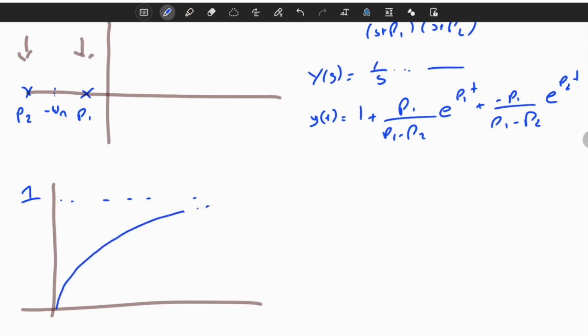Okay, so as you can see, it is very similar to the critically damped case. That's nice. Now the question is, how fast will it go, or which part will dominate the behavior? The basic idea is the fast part. Because this is constant, I have 1 and 2. The fast one will go to 0 quickly compared to the other one, and the behavior will be dominated by the slow pole.